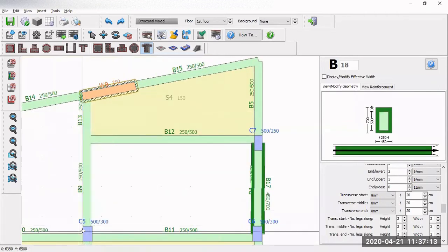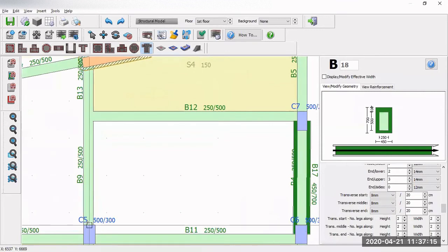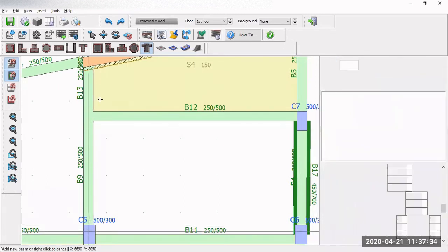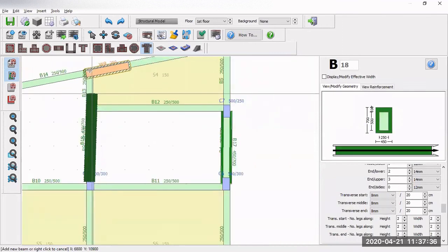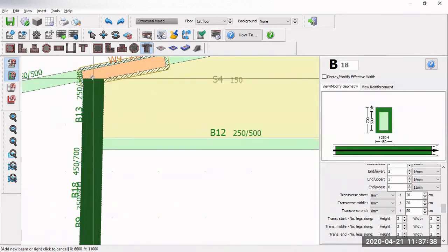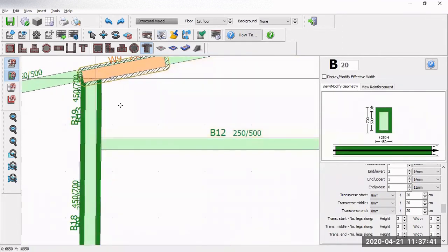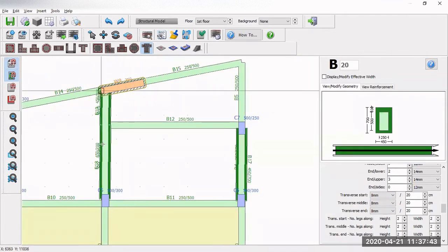In this example, we can start from here as well. You can start with any corners you want, like here. Maybe let me select this point to object and to drawings, the snap. Yeah, from this corner straight up to the shear wall. To wall. Yeah. So you can see that it automatically inserts the beam for you already.